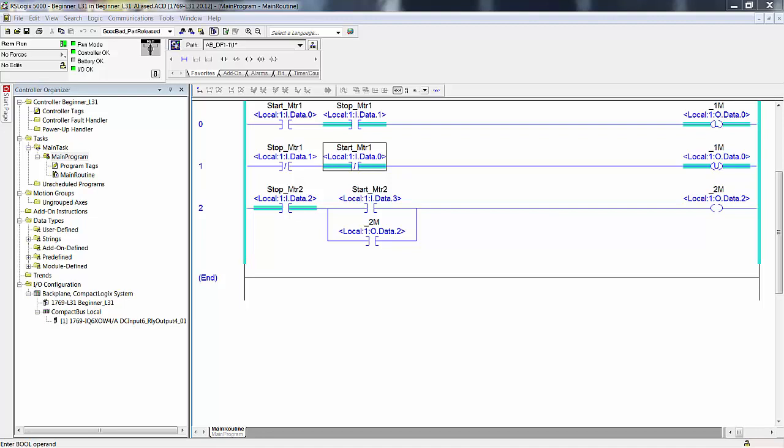Considering the lab that we just did and just discussed, you already are getting ideas. We want a system start and a system stop push button. That could sound like one push button, but we want a system start push button and a system stop push button that enables the conveyors to run, enable only, not run, enables them to run, or disables them from running.